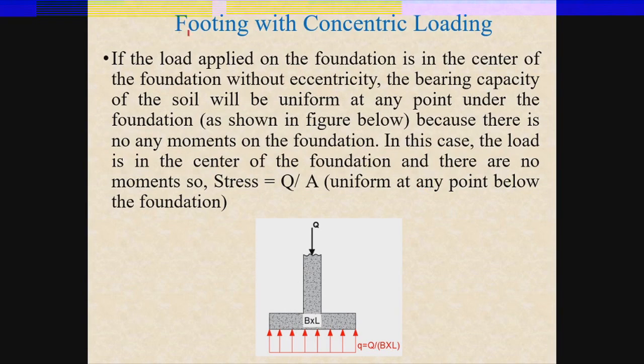Now guys, let me first discuss the case of footing subjected to concentric loading. So guys, when the center of the column and the center of the footing are the same, then in that case the footing is said to be subjected to concentric loading. In this condition, the pressure beneath the base of the foundation will be uniformly transferred to the subsoil.